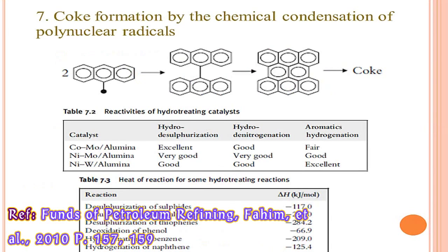Actually, hydrogenation is a very important reaction in the regeneration of the catalyst when the catalyst is deactivated by coking deposition. I think we mentioned it before from the previous chapter. The reaction showing here is a coking formation, which is the reverse reaction of what we are talking about.